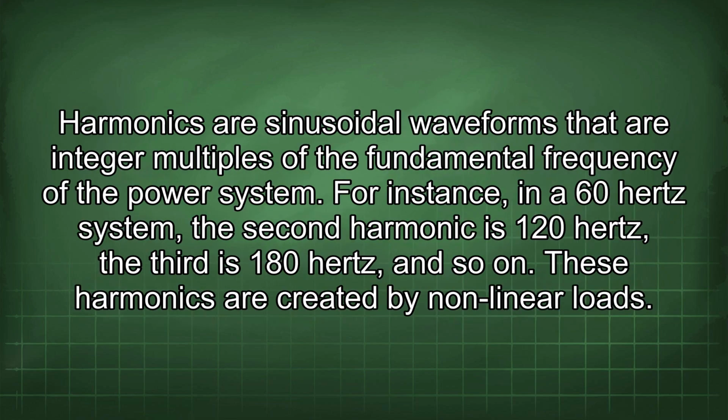Harmonics are sinusoidal waveforms that are integer multiples of the fundamental frequency of the power system. For instance, in a 60 Hz system, the second harmonic is 120 Hz, the third is 180 Hz, and so on. These harmonics are created by nonlinear loads.